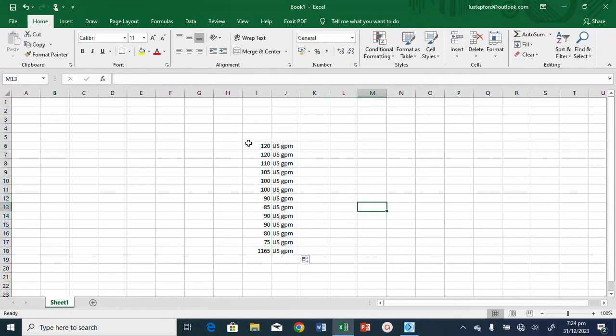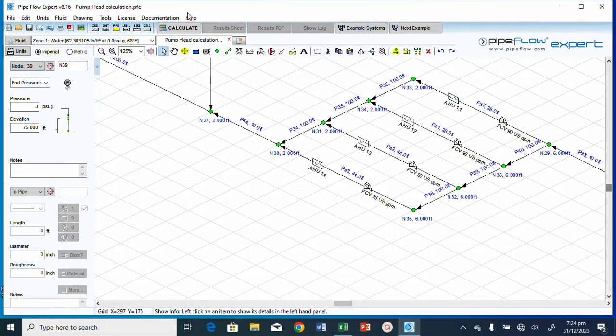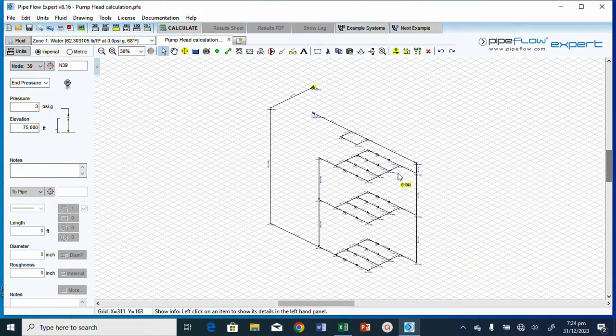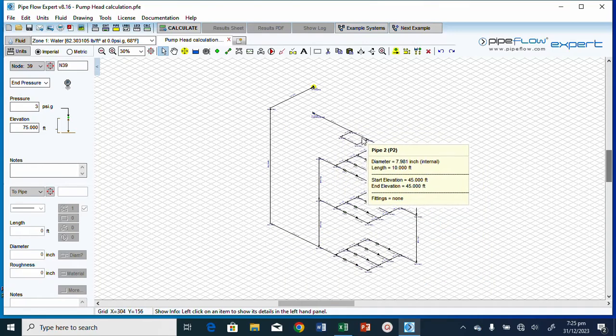So now, having known that, when you look at it, we have defined the flow rate from this down to all this. So if you sum all of them, you know the total flow rate that's supposed to be flowing from this point down to this point and back. Having known the total flow rate, we are going to use fixed flow to select the pump.